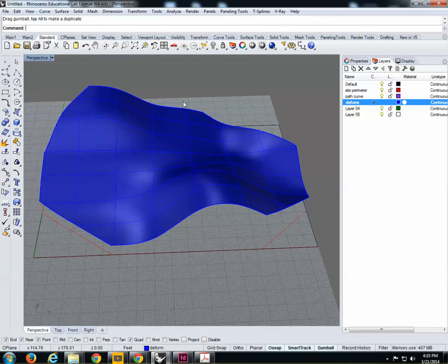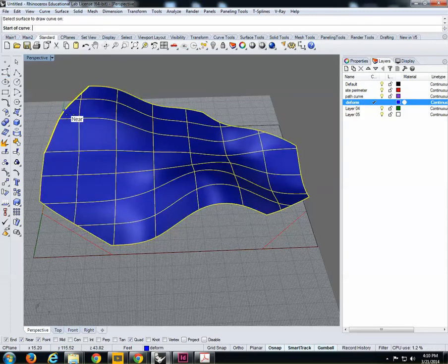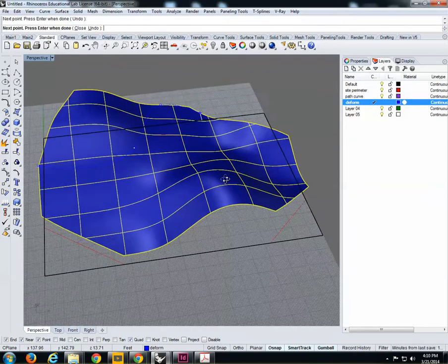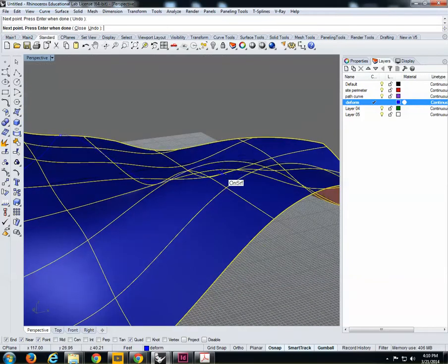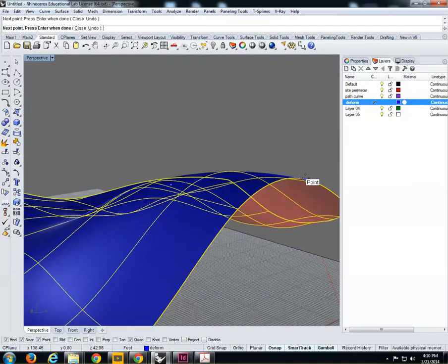Interpolate curve, yeah. So you can either type interpolate curve, or let's visualize it. If you go under the curve options and you hold your mouse, you can see in my screen there is the third button here that says interpolate curve. With this command you can basically draw whatever you want on top of any regular surface. So okay, I need to first select my surface and then I can start drawing any curve I want, and I know that this curve belongs to the surface. Of course I shouldn't snap to anything else down here.